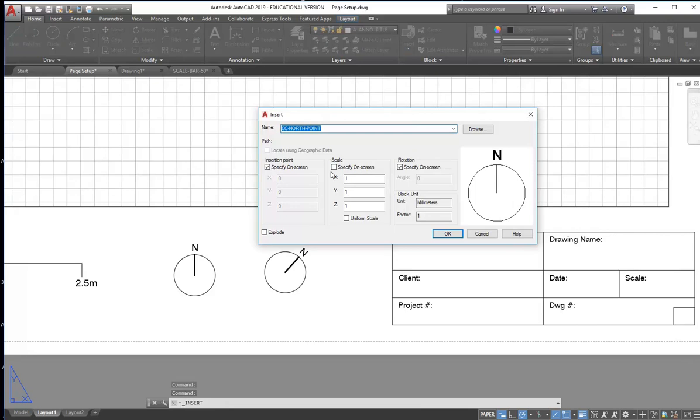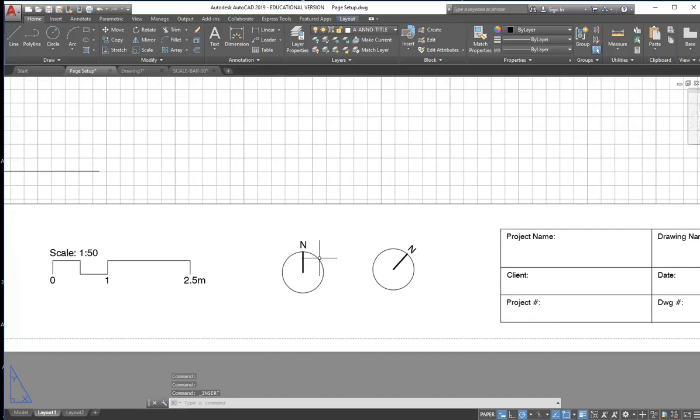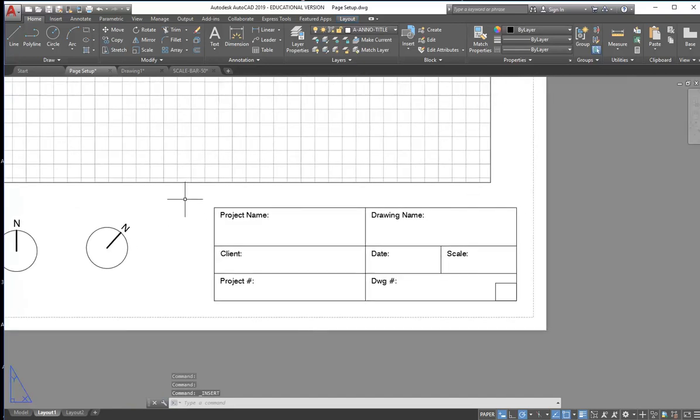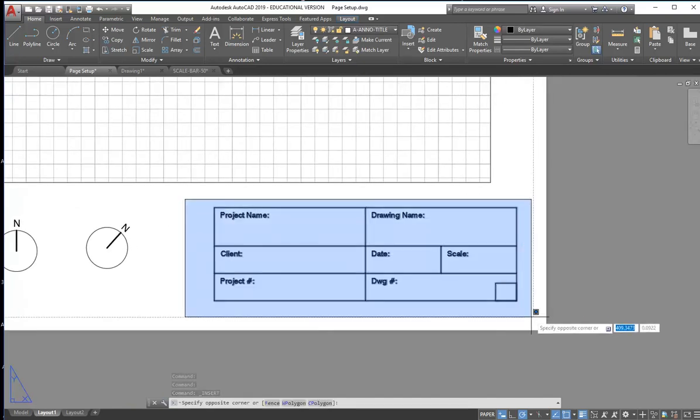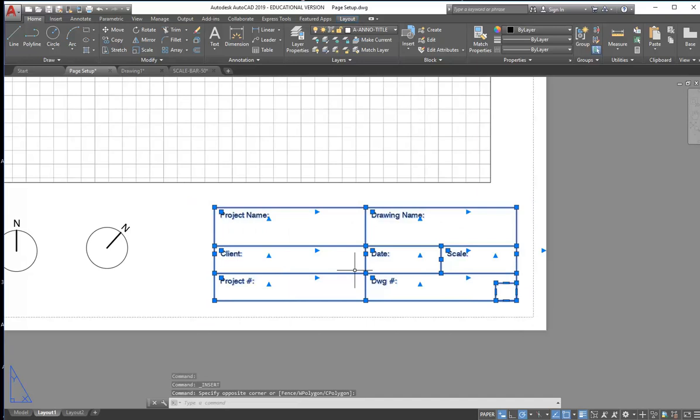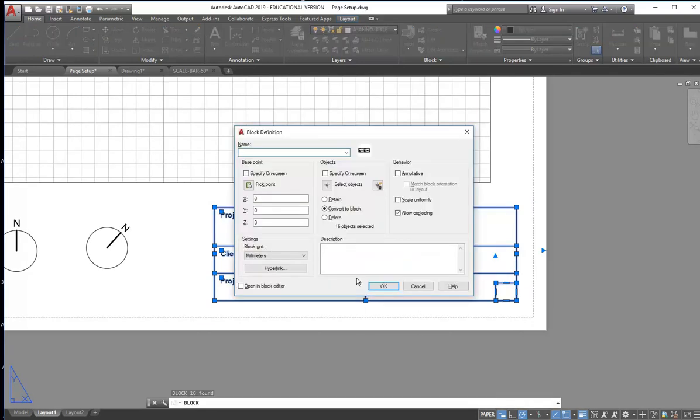And it's good to remember there are three things you've got to give a block to make it work. And I might even just show you again if I start with this title block, and then type. I'm actually going to start with a block because it's a bit simpler. B enter, of course, brings back that dialog box, and then you can see you've basically got 3 things to remember. And it helps to remember that because there's one that you'll often forget.